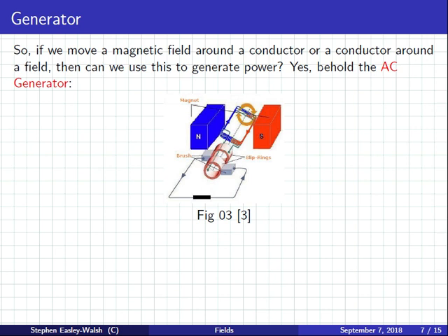Whereas here, you put one wire through the first circle and connect on the second circle, and this turns around. And here you have one wire and it connects to the first circle. This is a brush and this is a brush. As you turn this, you get a current. It comes out the first ring, along in the second ring, and then back in.